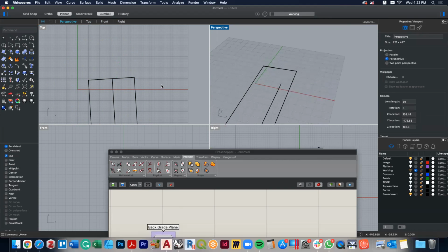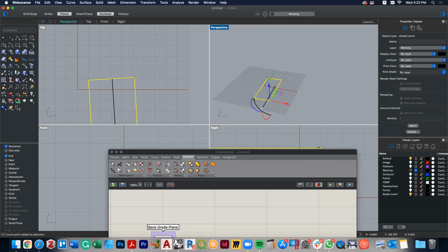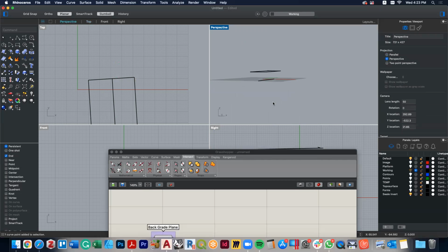And so that's really important that you know that you're snapping to that one. And so because of the fact that I made this 100 and it's 1 in 50, I'm also going to do, as I did before, I'm going to move this down -2 because it was 100 meters long at a 1:50 gives a 2 meter change in level. And so now I have that there.